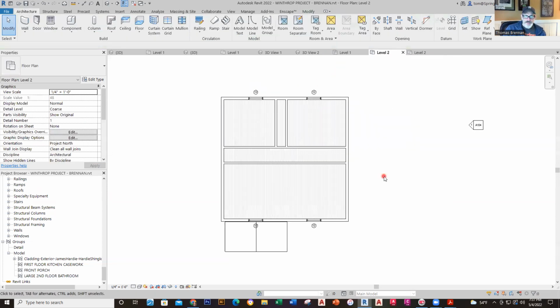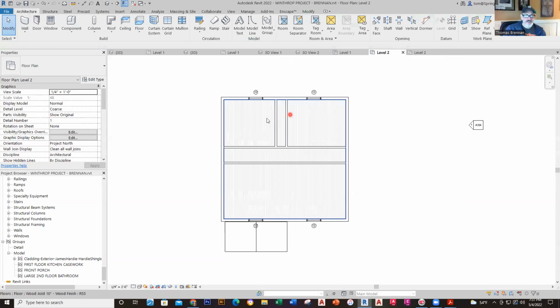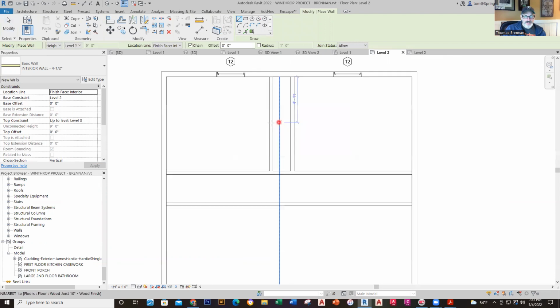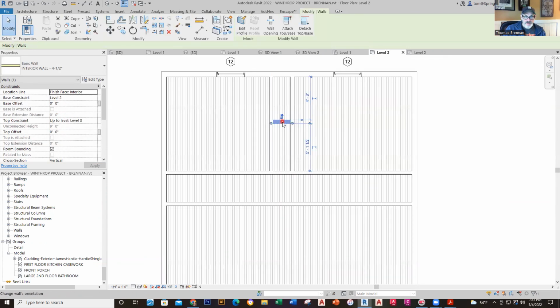Now at that point, all right, over here, so I've got those in place. And so now this one's a 5 foot 3 right there. And then I'll put in the other. So I'll put in a 5 foot 3 wall to divide those two. And this is just an interior closet wall right here. Let's say 5 foot 3. Okay, so 5 foot 3.